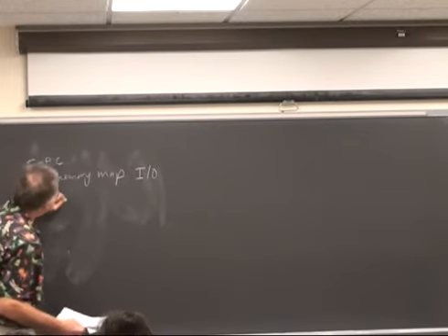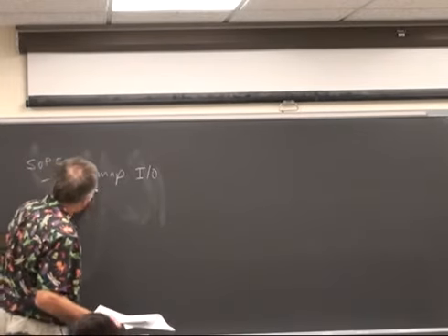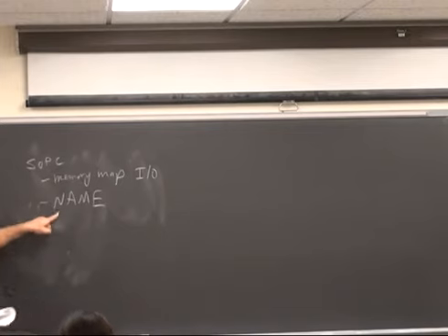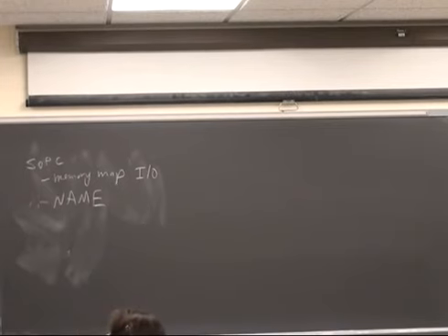You get to name each peripheral. And the reason I'm putting this in uppercase is that whether you use lowercase, uppercase, or mixed case in SOPC Builder, the output of SOPC Builder always uppercases it. It's ugly. So you may as well give the names in uppercase.